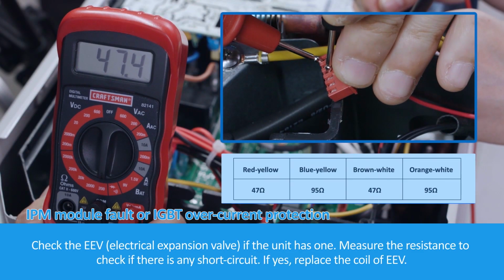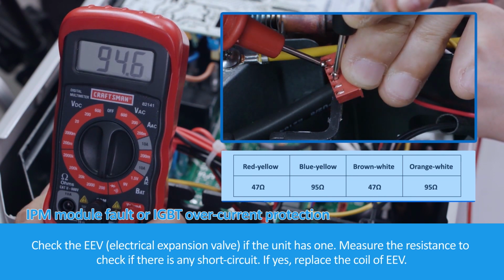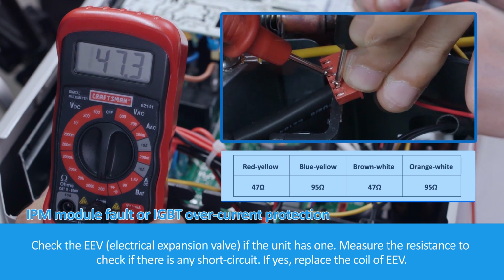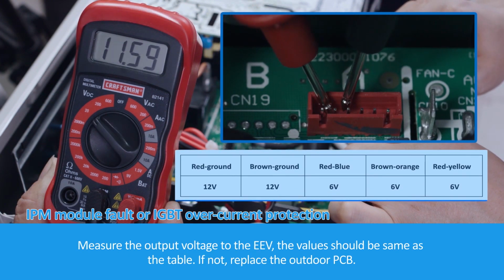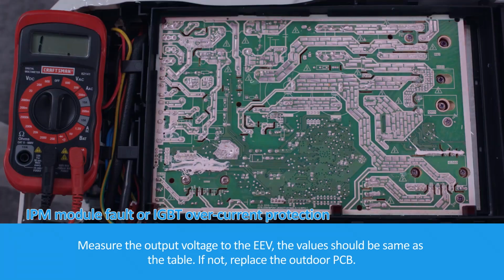Check the EEV, electronic expansion valve. If the unit has one, measure the resistance to check if there is any short circuit. If yes, replace the coil of EEV. Measure the output voltage to the EEV. The value should be the same as the table. If not, replace the outdoor PCB.